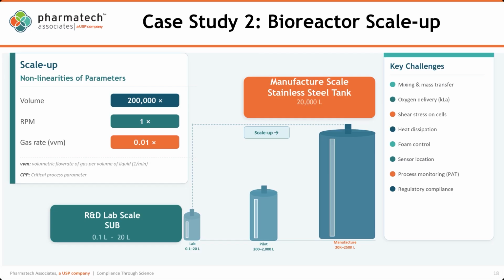What we're doing is we're getting rid of these intermediate experimental runs that we had to do in the past to sort of begin to understand the scale dependent, scale independent parameters as we moved up along the way. And it's allowing us to lower the regulatory risk because we're describing a relationship mathematically in silico to complement your empirical data. It's always calibrated or verified and then ultimately validated with empirical data. But that gives you huge advantage at the end of the day, and I'll show you that.